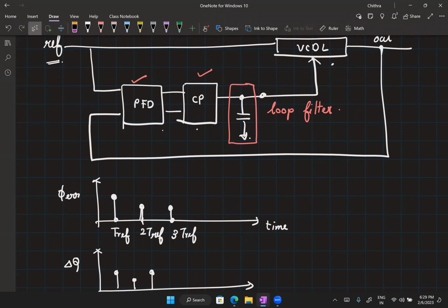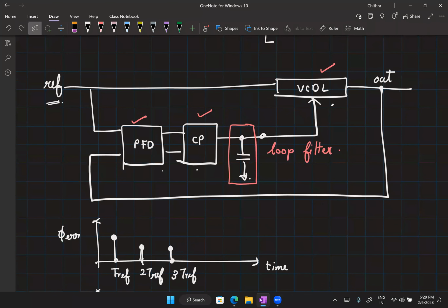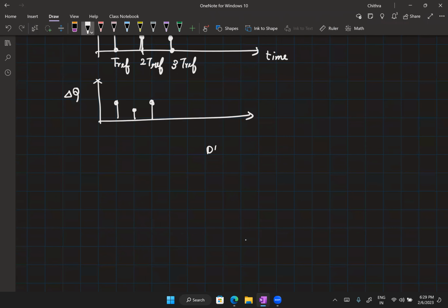Now, all this confusion is happening because this DLL is actually a hybrid of both continuous time and discrete time systems. There are parameters that are purely continuous time in nature, but there are blocks in the circuit that are discrete time in nature. We can potentially model this as a hybrid model, but then it will get too messy and become harder to deal with as designers.